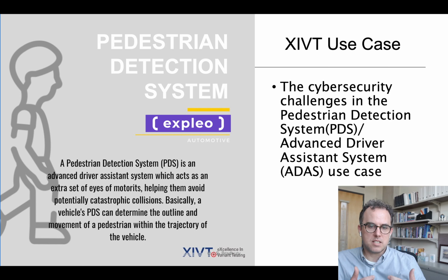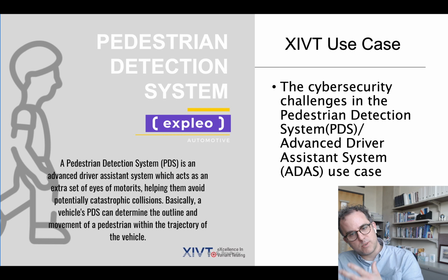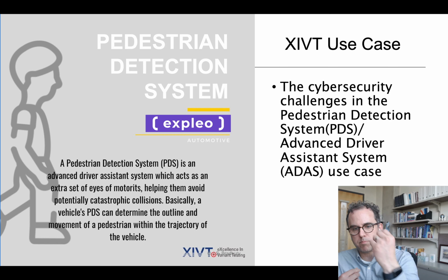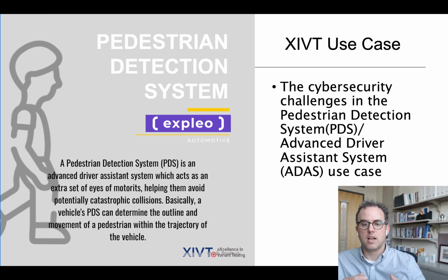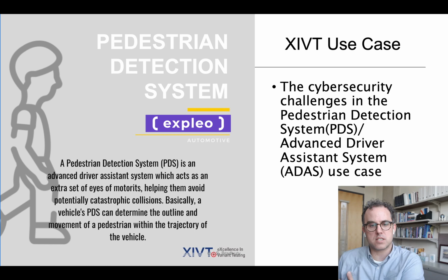With these attacks, there are known types of attacks, like I mentioned with the denial of service or the fuzzing attacks. There can also be hybrid attacks where they use some combination, right? A whole bunch of denial of service messages plus random data. You could also have targeted attacks, which spoof a real ECU or take it over and send out nefarious messages that are just slightly off in terms of the data. You can't always predict every kind of attack, and you need to be resilient to unknown attacks as well, which is why we focused on telling the difference between abnormal and normal behavior rather than detecting attack X, Y, and Z.